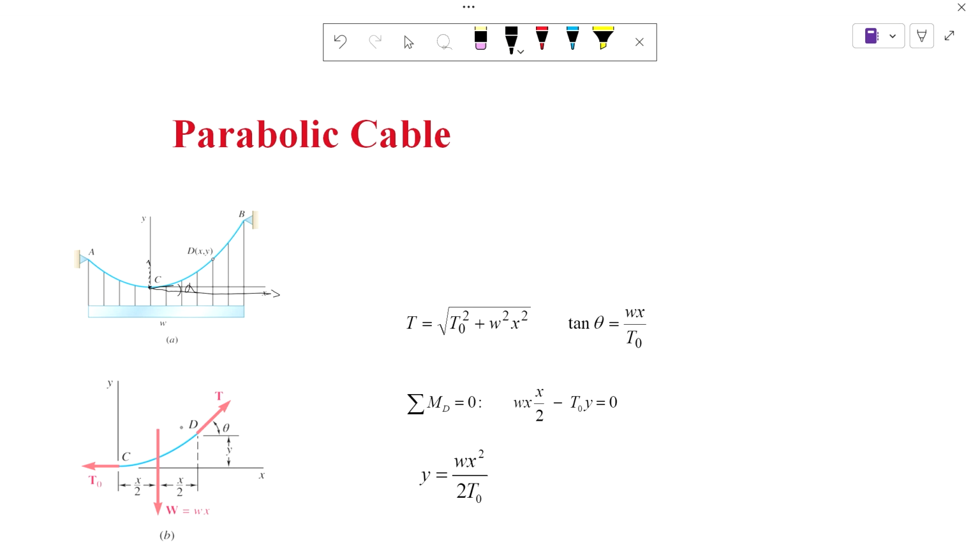So as we said before, the weight of the cable or the distributed load could be either or. Could be the cable plus a load, or it could be a load that is distributed across the cable, like in a bridge. You find that distributed load as we have before. That is going to be W. It is usually W times X, but really what it means is the area under this curve. And if you cut at C, you have this area and that area. Area to the right and area to the left.